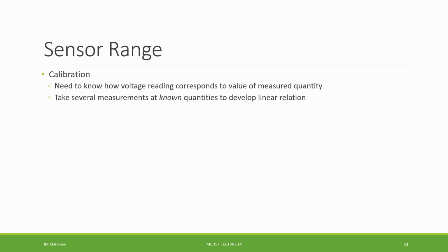A lot of times these calibrations are done statically, so we have our water at a constant 0 degrees. We take our measurement, so we give the thermocouple time to get down to that temperature, or we immerse it in the boiling water, we give it time to get up to that temperature, and we get that reading.